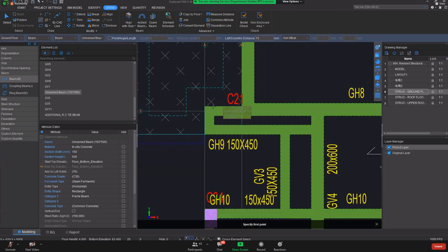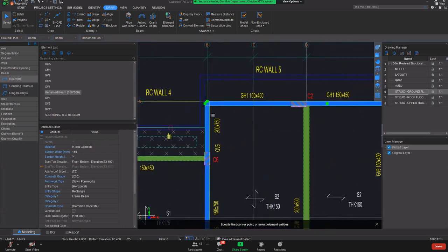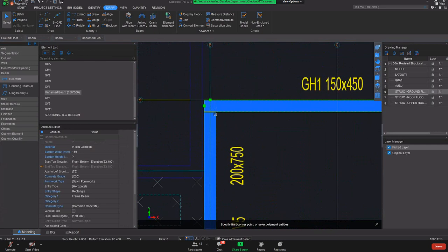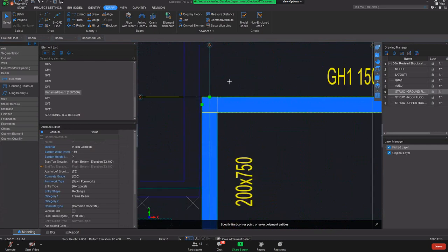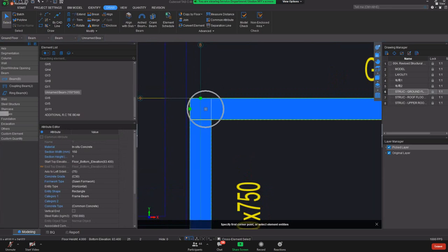One more thing to highlight to you. In fact, when we auto-identify the beam, it will be extended end to end. Some of you will ask me whether I need to draw it center to center, and for example, whether I need to draw until the edge of the adjacent beams, or whether I need to trim down.